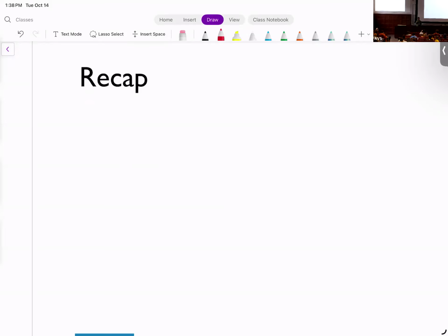There are 2 solutions. Solution number 1 is that you can stall. You have this thing called the hazard detection unit that sees that there is a dependency between source and destination and stalls the processor. How do we stall the processor? We insert bubbles and we stop the fetch and decode from advancing, okay? But stalling means that I need to waste 2 cycles to fix the data hazard problem, right? I don't like that. I want to be able to run the processor all the time. So I introduced the second concept called forwarding.